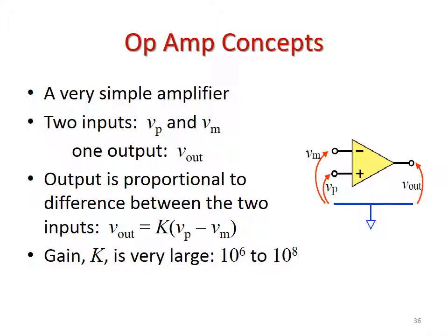And so we've got an internal gain of that op amp, which is extremely large. A gain that large essentially means if there's any noise or any difference between the inputs whatsoever, it's going to send all of the voltage to the V out. So this isn't a very useful signal except if you're comparing two things together or checking if something is on or off. And even with that, it's a very noisy signal, because any time the input goes above or below, it's going to turn the signal on or off, because our gain is so very high.